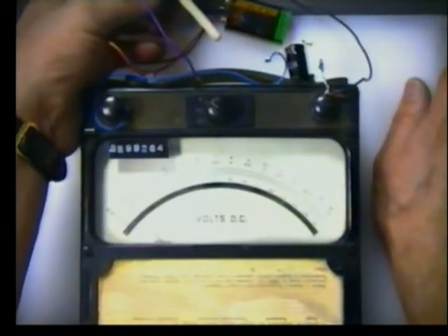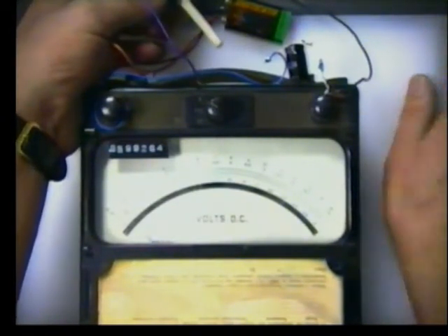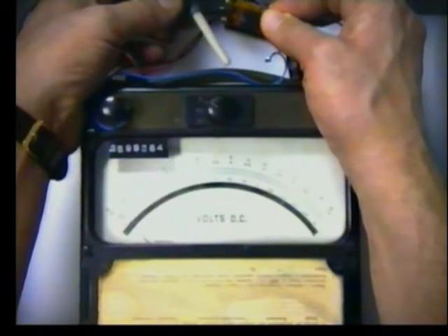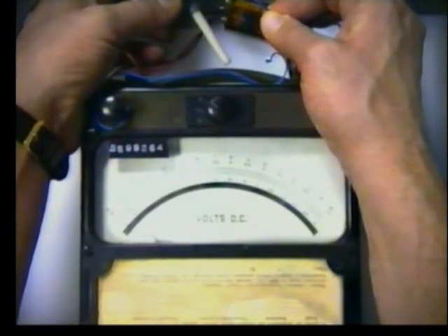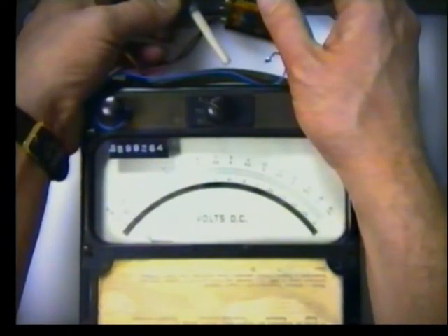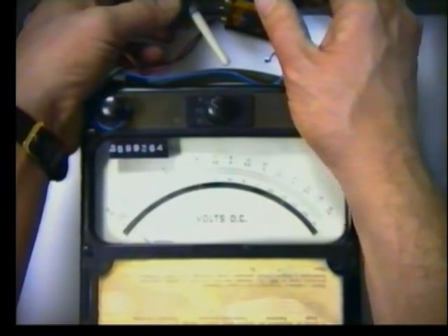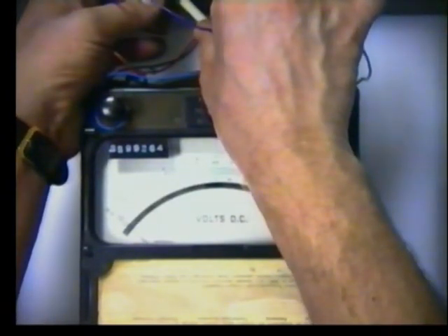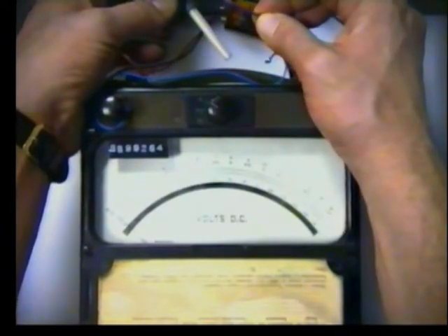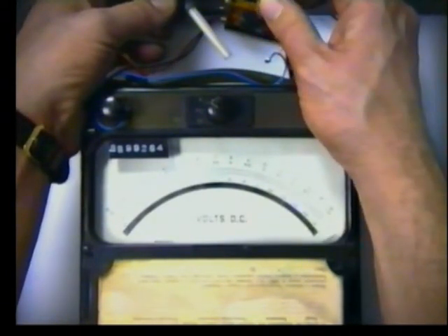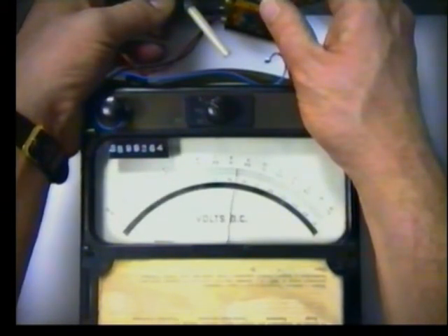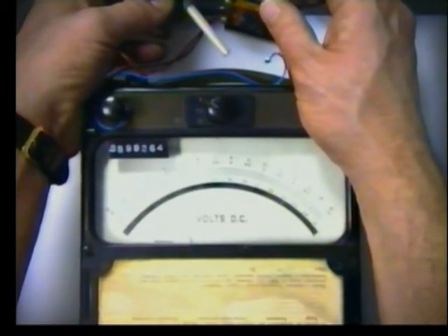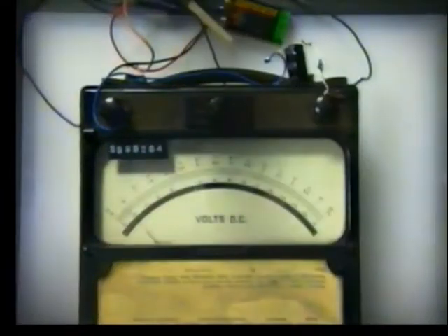So the way that an ADC works, a dual slope ADC, is we apply our unknown voltage for a fixed period of time, 1, 2, 3, 4, and then we time how long it takes to discharge. Obviously the further it manages to charge up in those 4 seconds, the longer it will take to discharge. So here we go, 1, 2, 3, 4, and now we let it discharge. The higher the input voltage, the longer it takes to discharge. So there we have a simple demonstration of a dual slope ADC.